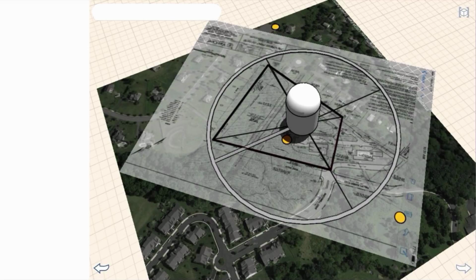One of the things that I like to do, I showed this at RTC, is that when I start the FormIt model, I build a compass. I usually start with the compass and a solar dial, and I'll do some early analysis, before even looking at what the building is, to understand what the optimum solar orientation for the site is. Understanding that there are really no existing buildings around this project to cast shadow onto the building, they're basically at the top of the hill in the woods.